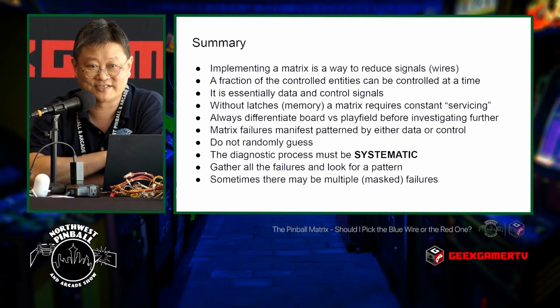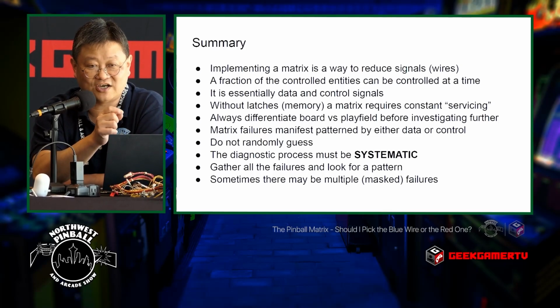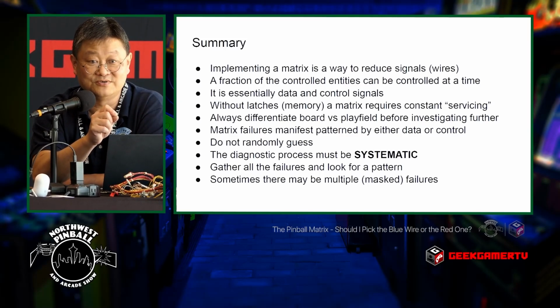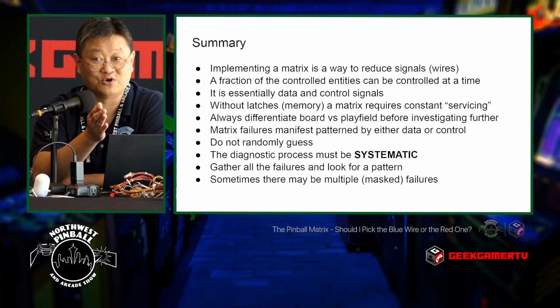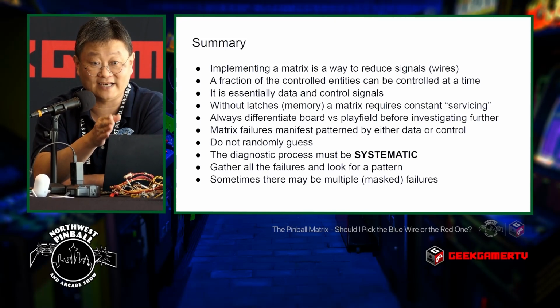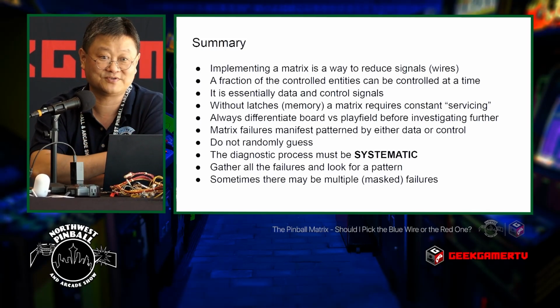The thing with the lamp matrix is that it's momentary. That lamp in column 1 is only enabled at the time column 1 is enabled. As soon as you enable column 2, the lamps in column 1 are off. So how does this work? Why do you see the lamps actually lighting up? It works this way because it works so quickly, and your human eye is slow to respond, that the human eye will perceive it as actually on all the time, even though that lamp is actually being turned on and off really, really fast.